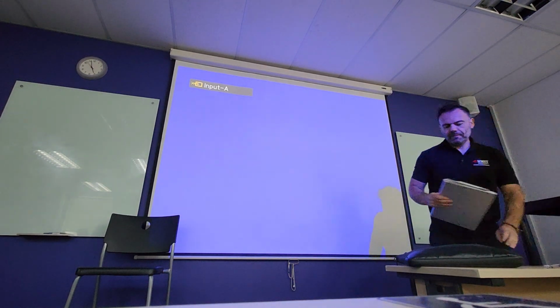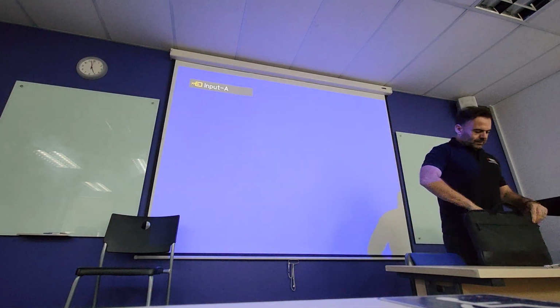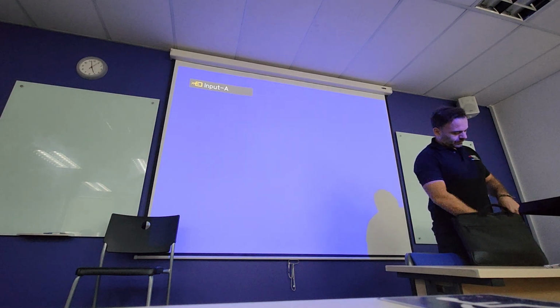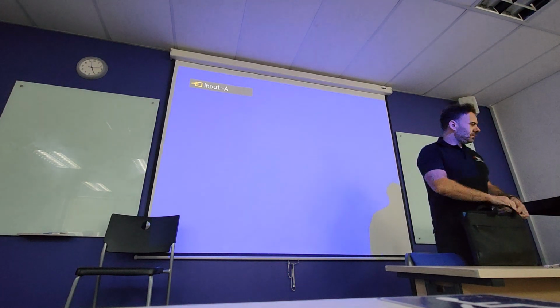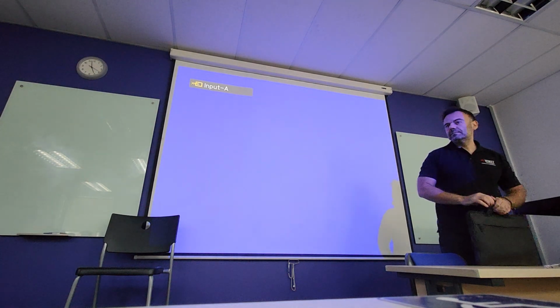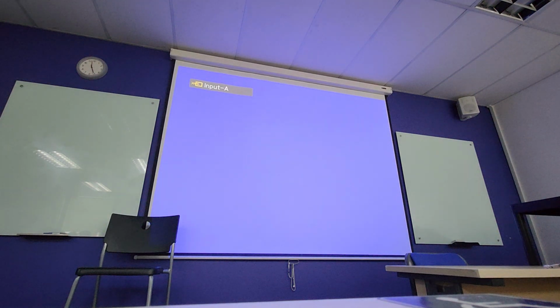So these are all within our parameters. Based on this, our deflection cannot exceed 0.15. This is 0.11, which is nearly the limit. This one got more deflection than that one, because this one is model 1 and this one is model 2. What I do is reduce the thickness to bring it closer to the limit. This one already passed. Okay, all the best, good luck on the exam, and see you at the graduation ceremony.